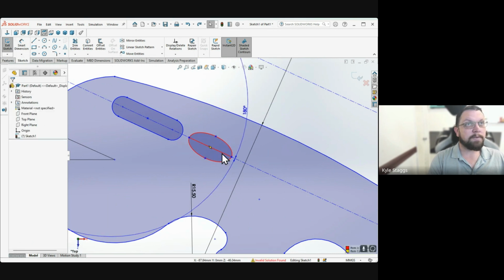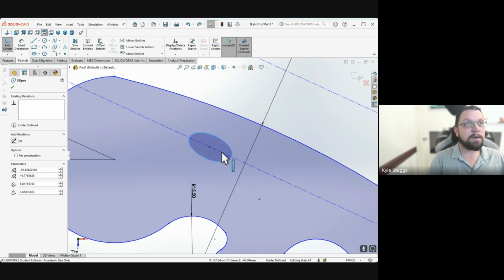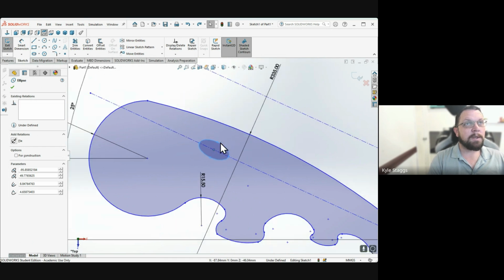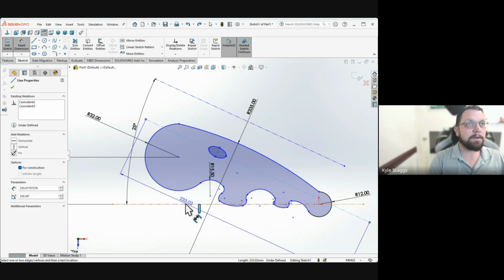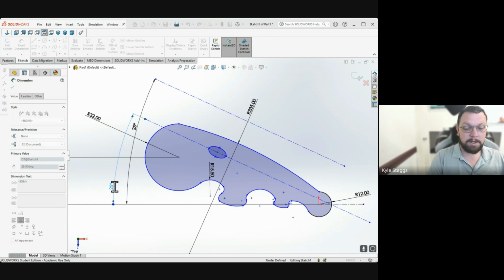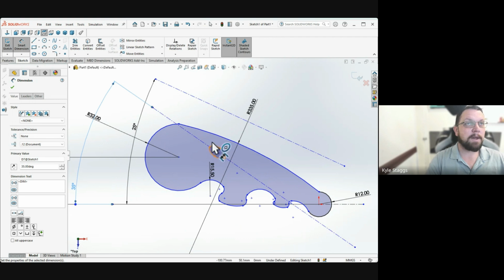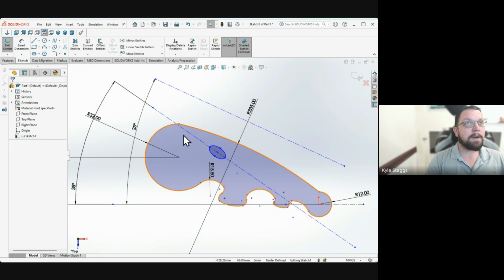So what you would actually have to do is set that ellipse at its own angle and add another angle reference. You would move this using the smart dimension and say, maybe that needs to be 35 degrees or something of that nature. And then I need another center line that allows me to have a different orientation even still.